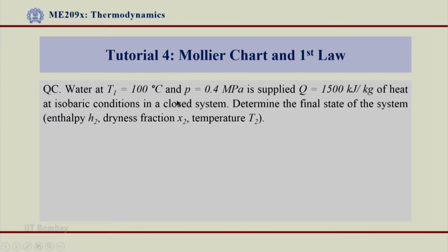Let us now again understand, we can possibly have a cylinder piston arrangement, have state 1 in that and state 2 can be found out. So, always try to draw some kind of a cylinder piston arrangement or a schematic to show the system first. Try to show your system also on a PT diagram if we are sure about the state, and that will actually clarify a lot of doubts. For understanding purposes, those things are always essential.